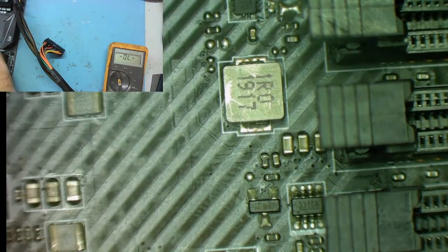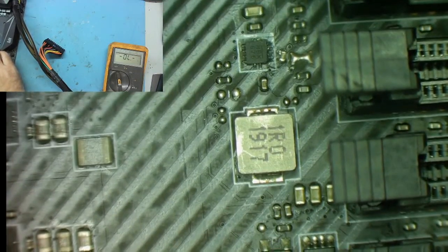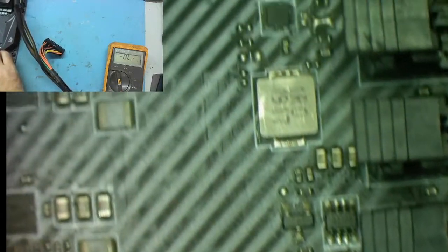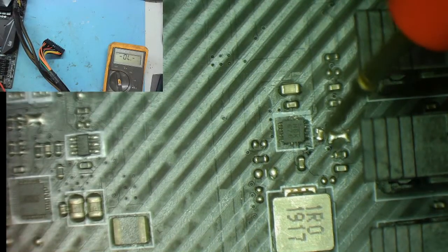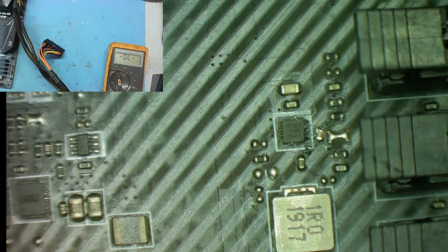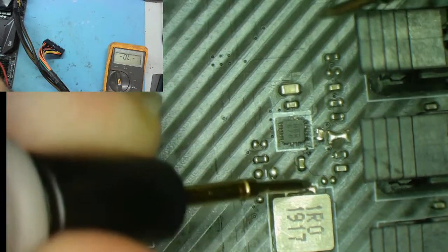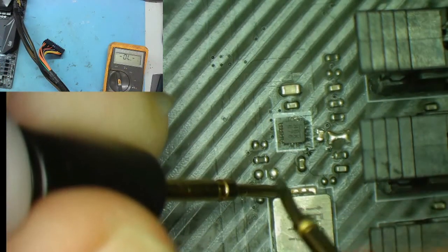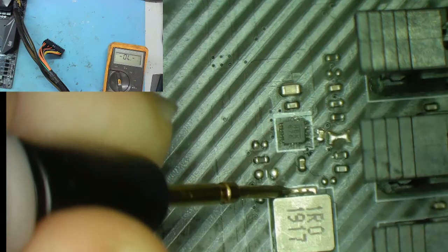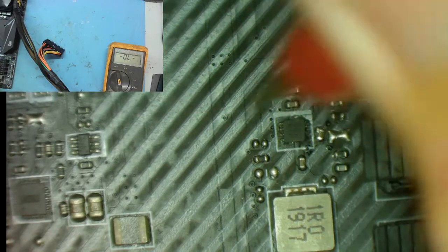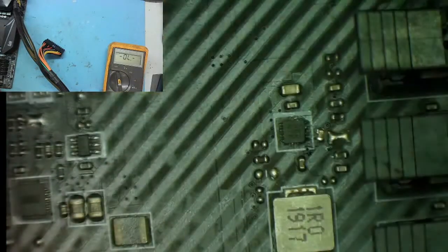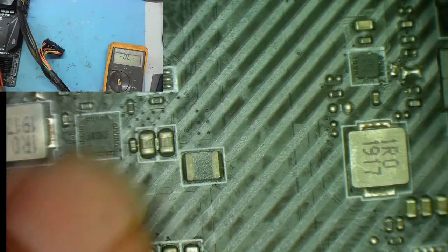Okay, so next thing is, why does this coil here only have 0.7 volts? Well, that goes to this thing, HBK 676. I think it goes to that because it's right next to it. I'm sure you probably recognise these circuits now, that there's a controller very near to a coil. So that's the controller. So I suspect the problem is either this controller's got a fault, or there's not a short circuit but a low resistance on this to ground, yeah? But if that was the case, it should get hot.